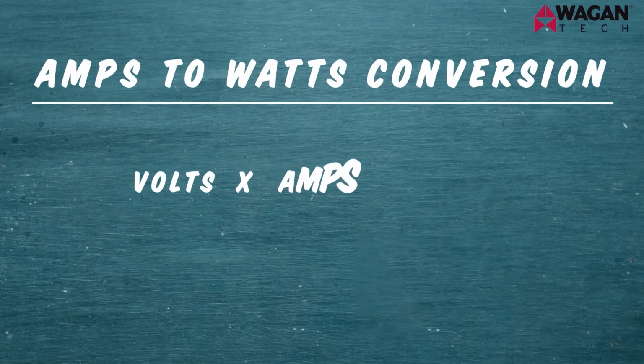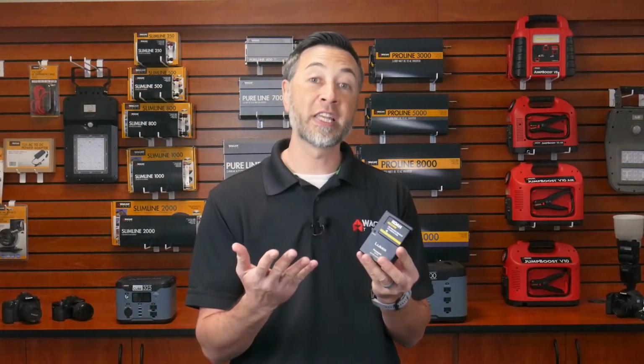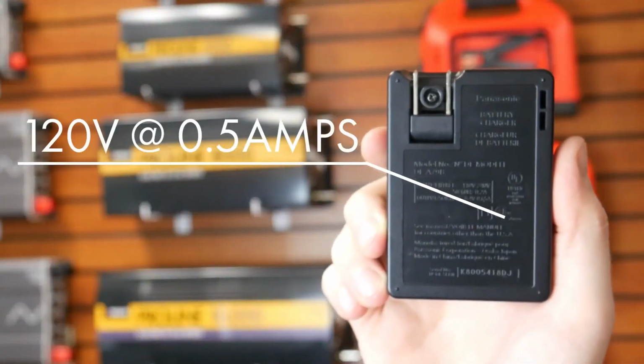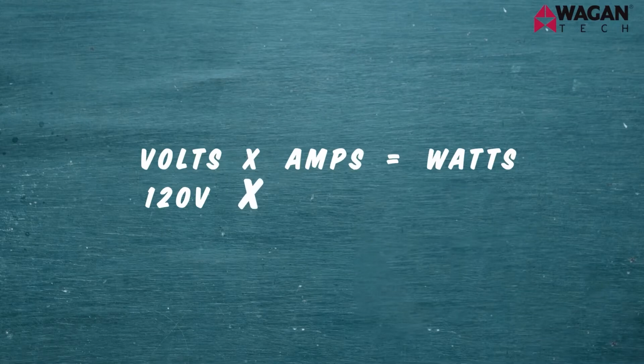If your device doesn't list the wattage, here's how you can calculate it. Take the volts times the amps and that equals watts. Let's take a look at this camera battery charger, for example. On the back, let's say it says 120 volts at 0.5 amps. So you take the 120 times the 0.5 and you get 60 watts.